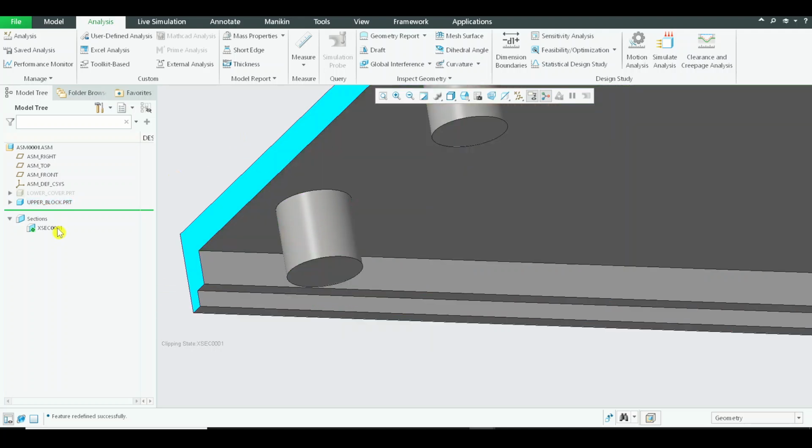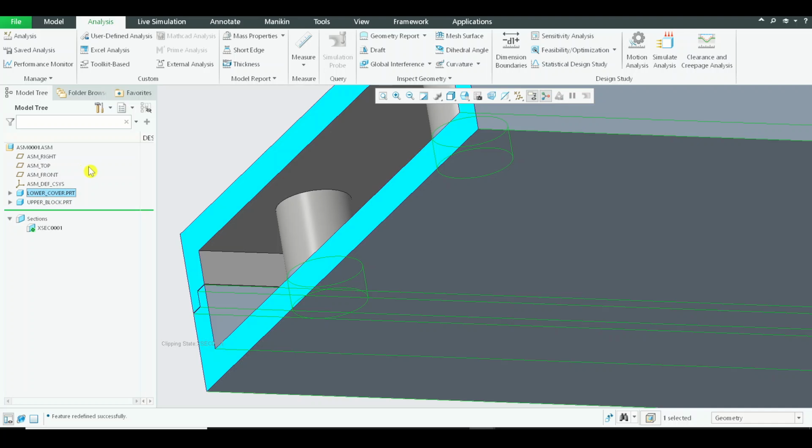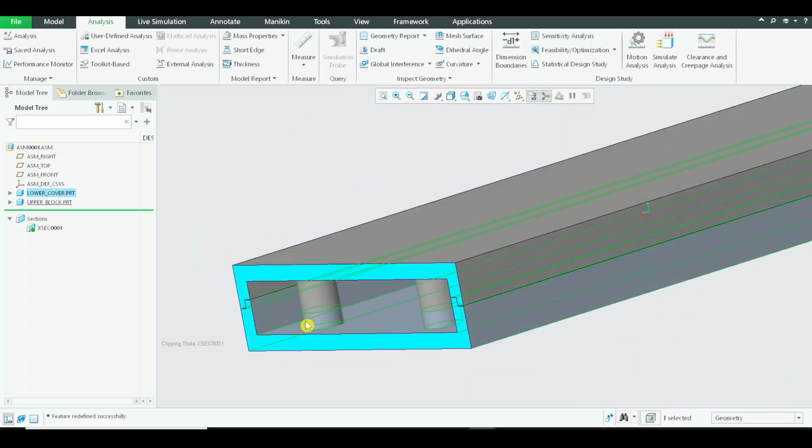All right, now I believe you have understood the logic. There should be two holes being created, the clearance hole and the tapped hole. The clearance hole diameter will be larger than the diameter of the thread, and the tapped hole diameter will be smaller than the diameter of the thread of the screw being considered. Now the next major question is, what kind of screw are we going to use for this connection, or for this assembly, or for this joint?